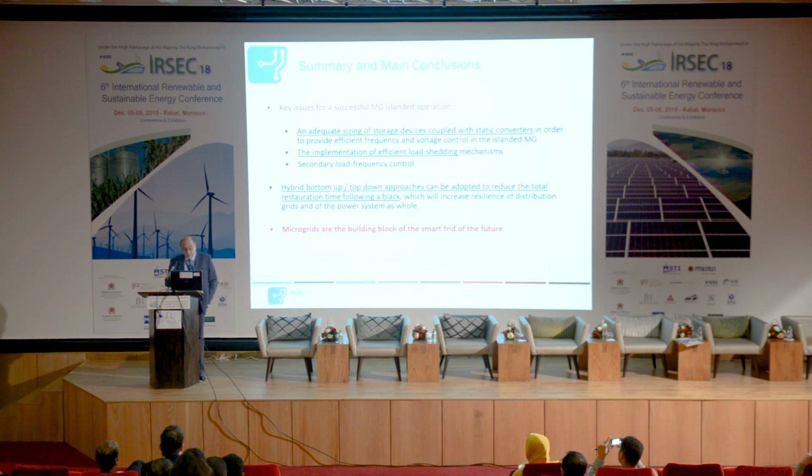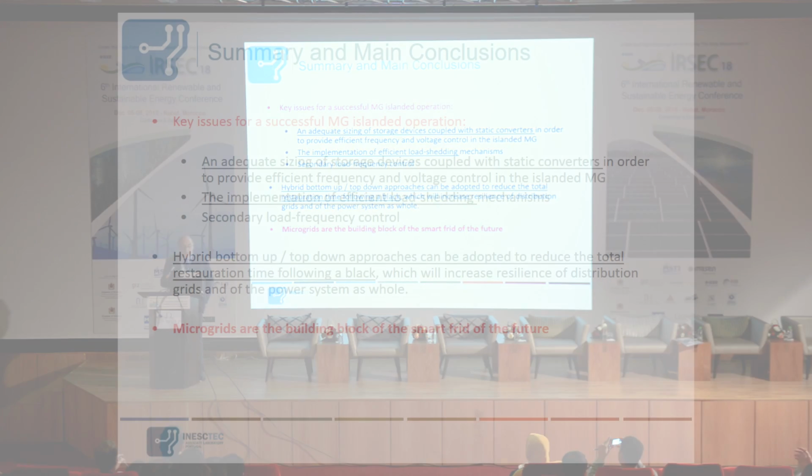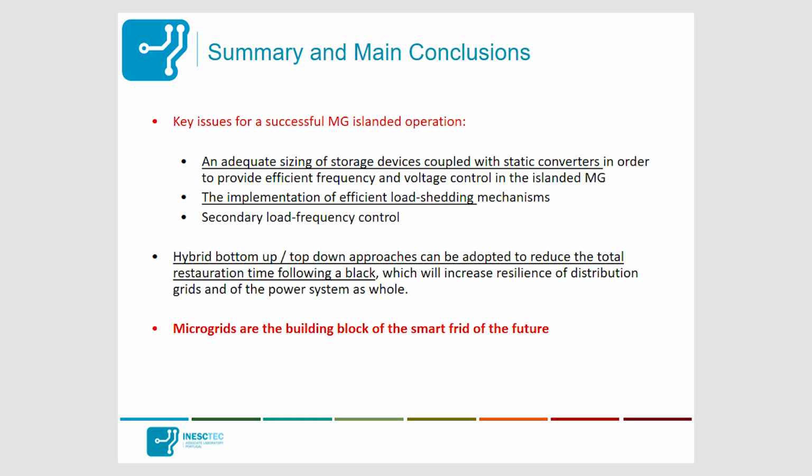And very, very important is the need of a secondary load frequency control. Otherwise, frequency will drift, will not return back to the nominal value, and it is extremely important to have it back to the nominal value. Otherwise, the batteries will keep on injecting power and will exhaust the energy that they have stored.